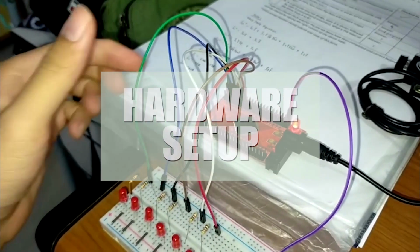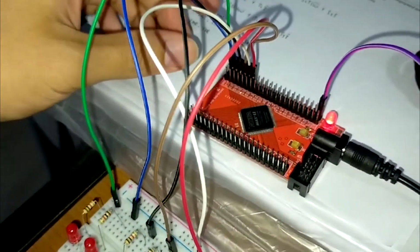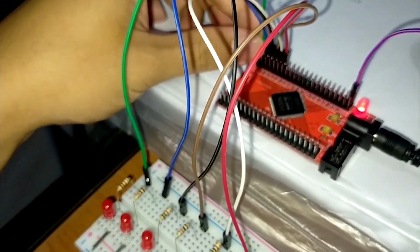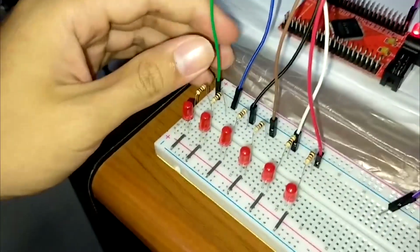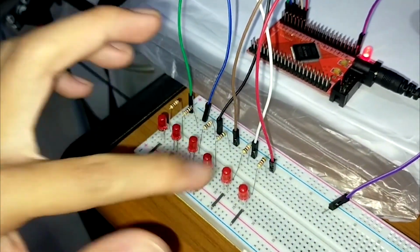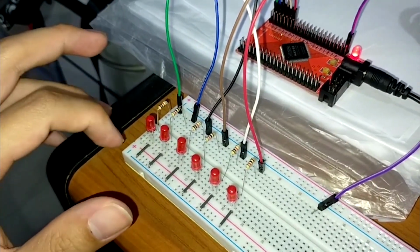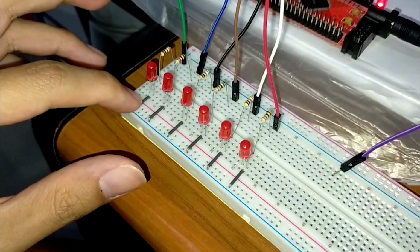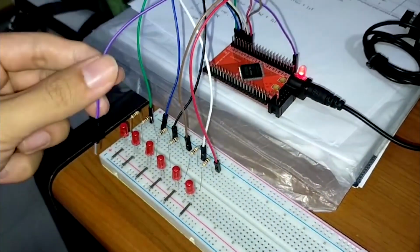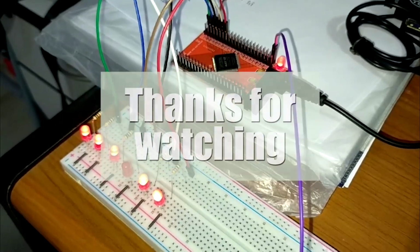To connect the CPLD with the breadboard, we use male to female jumpers. The female part of the jumper is connected to the CPLD pins that we assigned just now, and the male part is connected to the breadboard. This is the connection of the LED. We use a resistor connected to the anode of the LED, and the cathode of the LED is connected to the ground. Now, this purple wire is connected to the ground. If I plug in the purple wire, we can see the LED lights up.